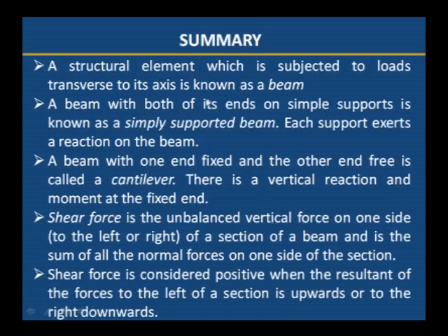Okay, so what we discussed today: a structural element which is subjected to loads transverse to its axis is known as a beam. That is the first point, we discussed the definition of a beam. A beam with both of its ends simply supported is known as a simply supported beam. The supports exert reactions. We have observed that if we want to calculate the bending moment or shear force diagram, we should calculate the support reactions for the simply supported beam.